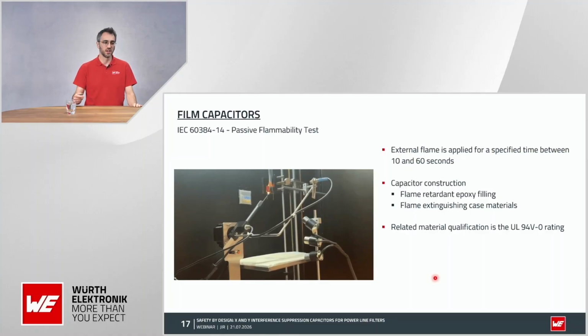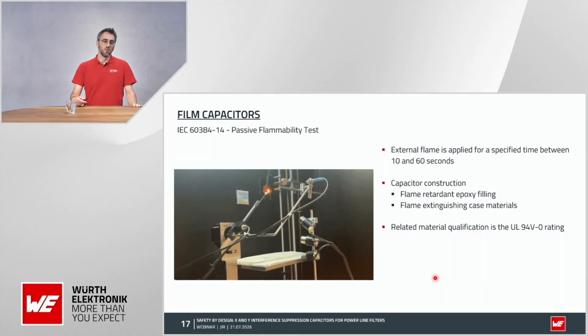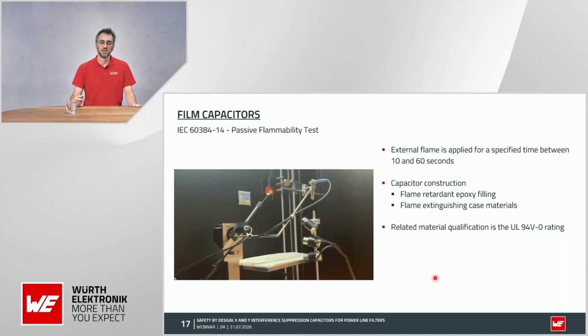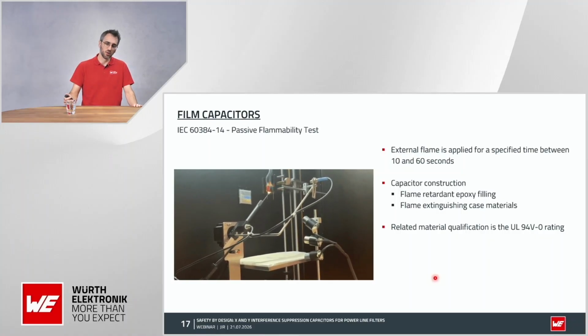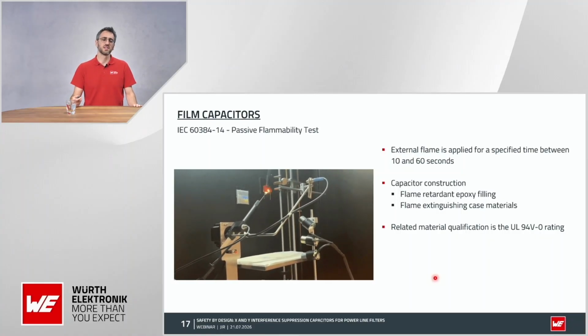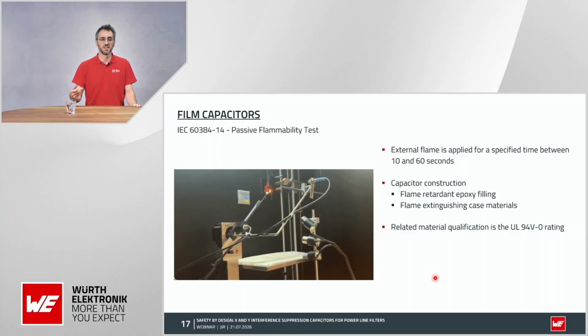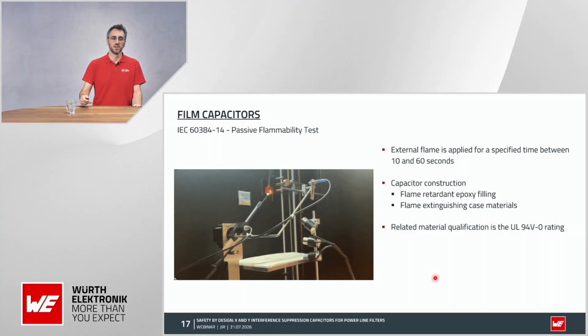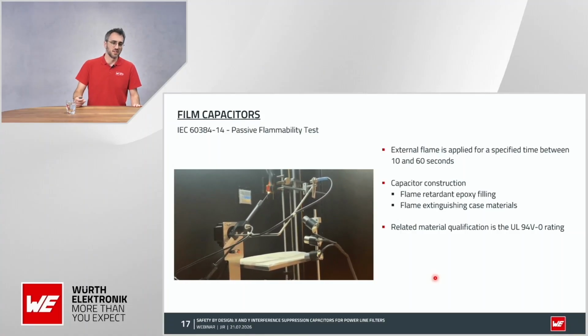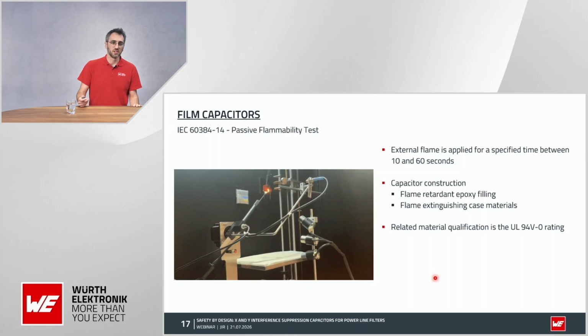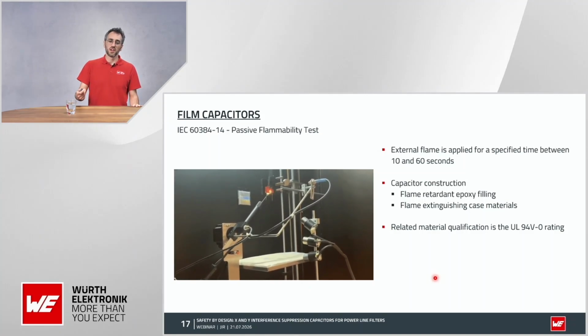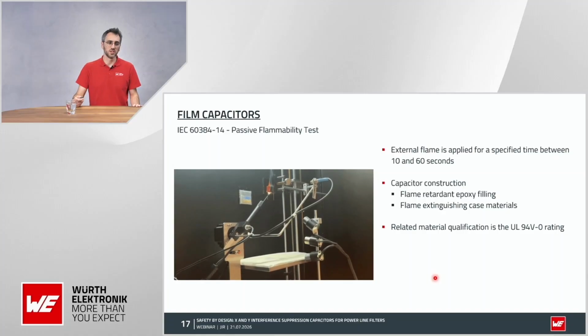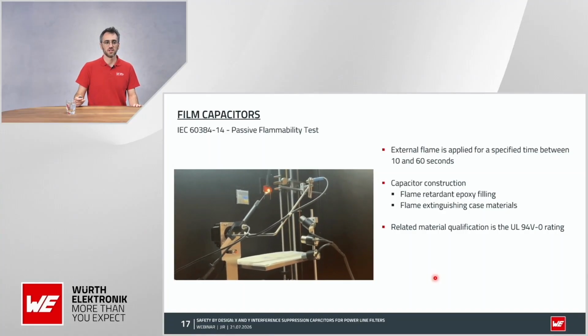now in this case also against fire hazard, where we actually apply a flame on the capacitor without electric load and check that the capacitor will not catch fire by itself. So when we stop the flame, that is applied for a time between 10 and 60 seconds, we are expected to see how the capacitor stops burning.